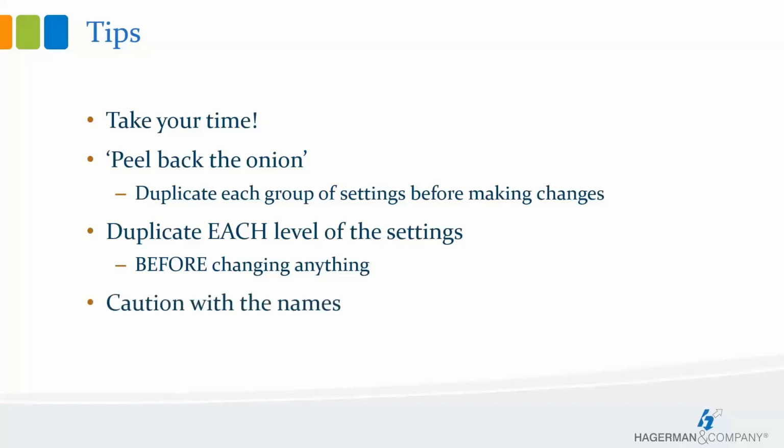And lastly, be thoughtful of the names that you use when you're creating your new styles and all of the sub settings. This will help ensure that they're easy to find later. I found that if I tack on the word custom, for example, to the end of my file names, but keep the rest of the file name the original, that tells me which style I started with.